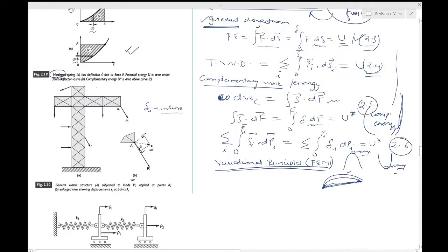So you have a system like this, in its equilibrium position, with the complementary energy U star. And you consider a small increment delta Pi to the load Pi. So to this load Pi, you consider a small load increment, an increase in this load, while all other loads remain fixed. Meaning, if you have chosen P1 with the appropriate direction, it should actually become P1.